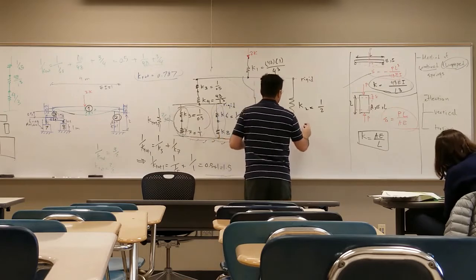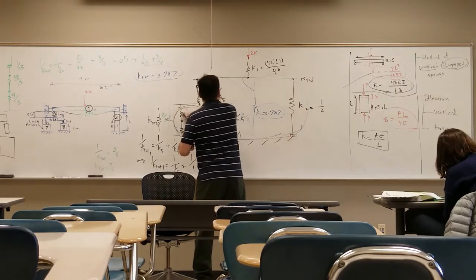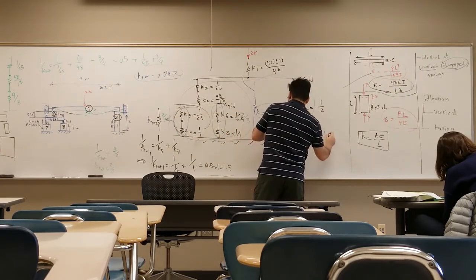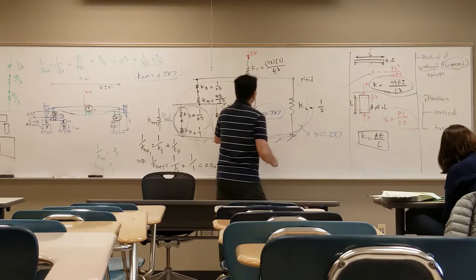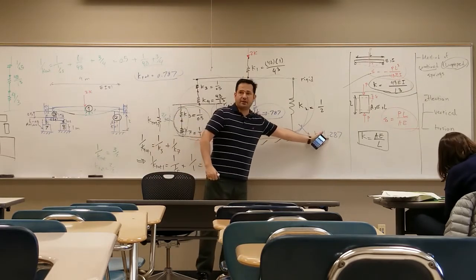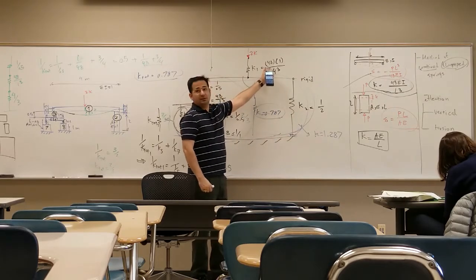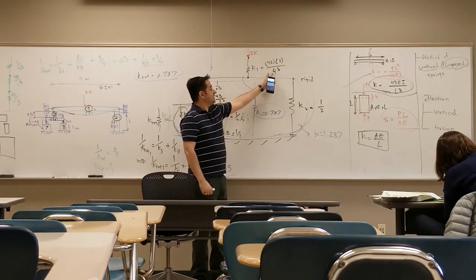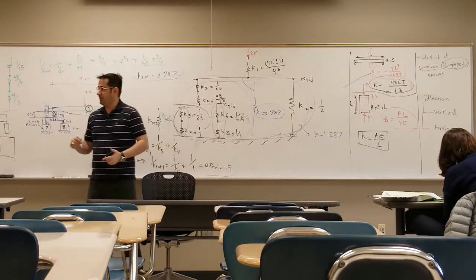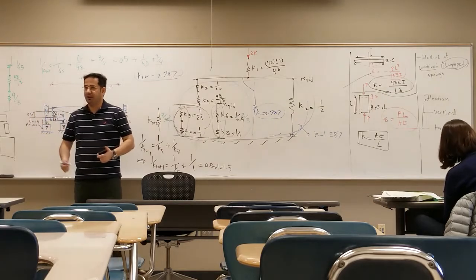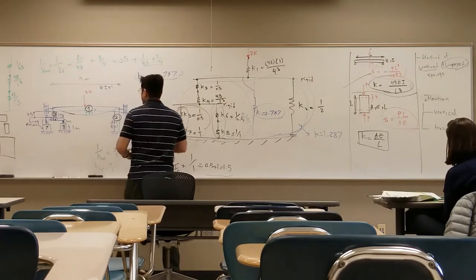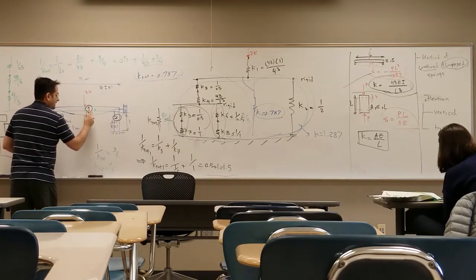Then you get the entire bottom, the spring constant is going to be 1.287. Now what should I do? 1 over 1.287 plus 1 over this guy, which is 4 cubed divided by 48, is equal to 1 over K total. Then you find K total. Now if you find K total, what can you write about deflection at this point, delta?